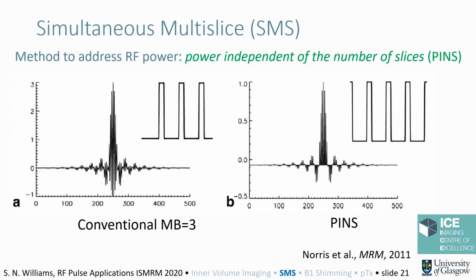Unlike conventional SMS with constant slice-select gradients, PINS pulses use small slice-select gradient blips whose area determines the period between PINS slices. The turning on and off of gradients, or discrete excitation k-space based sampling, is what reduces the RF power deposition. Nevertheless, the PINS approach does create an infinitely wide field of view in the slice dimension, which might limit its applicability to some applications.